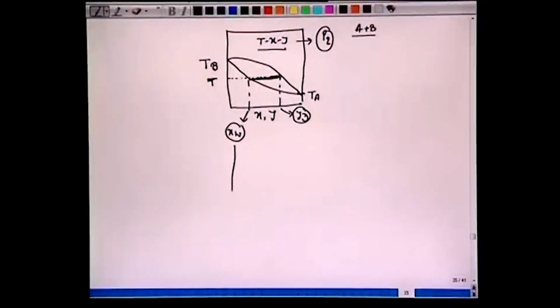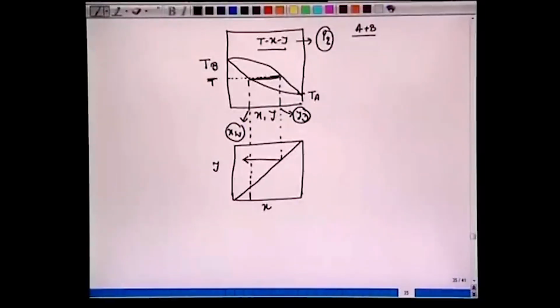Now let's plot, just underneath this, the y-x diagram. All right, we have done this earlier also. So, the 45-degree line. Now if we take this projection here on the y, go to the 45-degree line, go this way, take x all the way till here, it intersects here. These would be the coordinates, x being XW, and this would be YD. This point will be on this y versus x diagram, because the two streams leaving the flash drum are in equilibrium. So we have this point here, with coordinates XW and YD, and we must note that this coordinate also corresponds to this temperature T here.